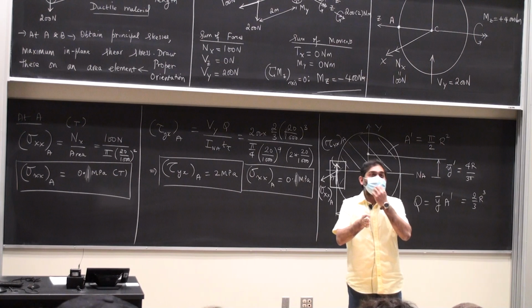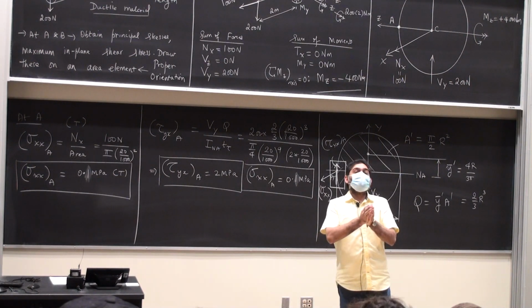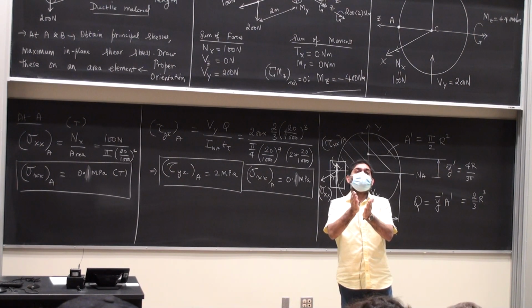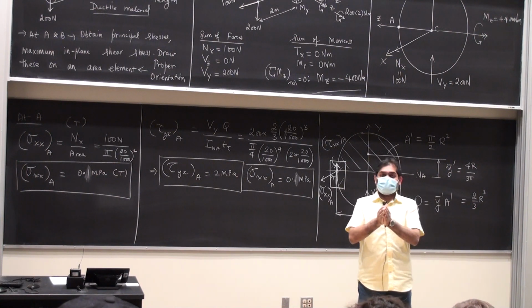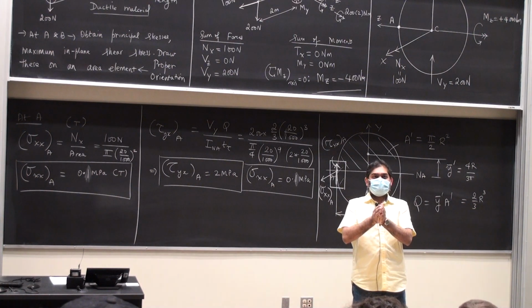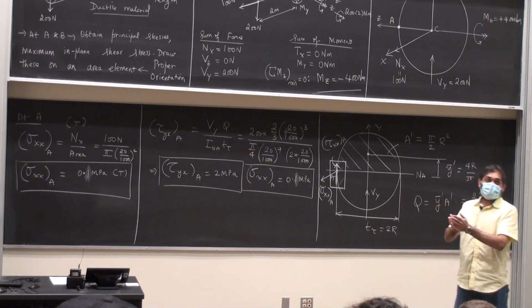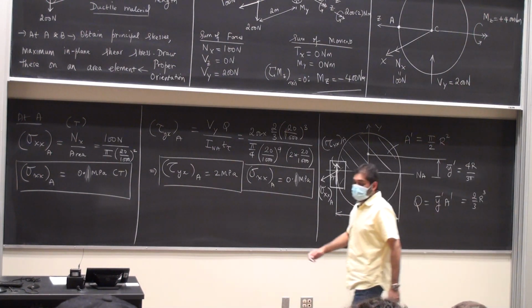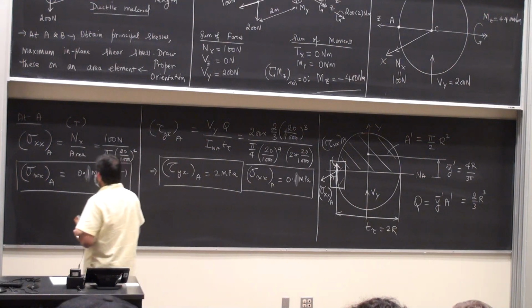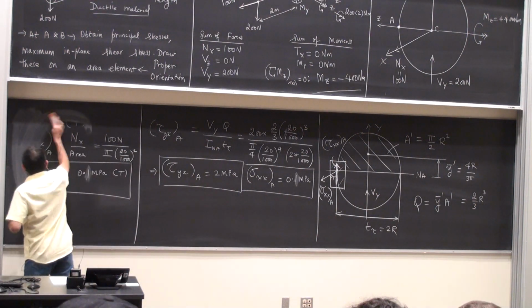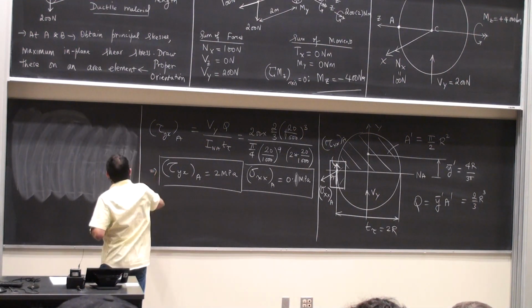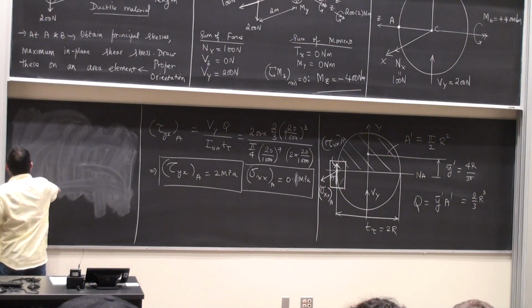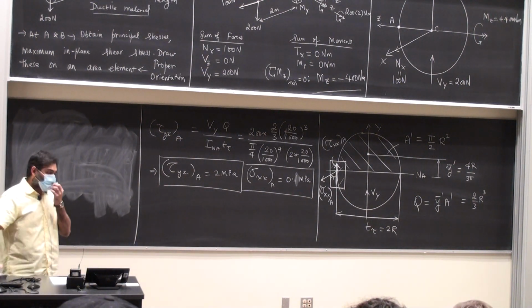When a body fails, let's say if it's a brittle body, you have to figure out which point on this body has the largest of those principal stresses. That is the trick. Which is why I am choosing 2 points here judiciously, trying to figure out which one is going to cause major damage. I'm going to clear this one. Draw the volume element. Okay.